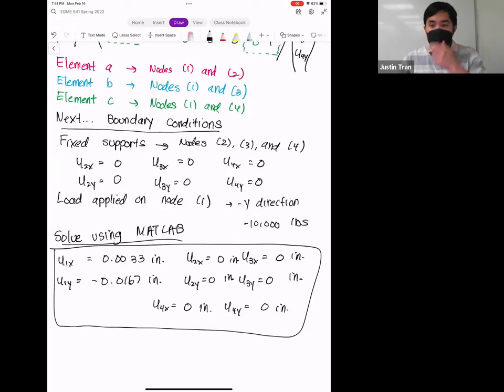All right, question. Can you incorporate this problem into Ansys? Yeah, absolutely you can. What you can do is incorporate each of these slender objects as a beam element, because Ansys gives you the ability to define these slender type elements. So very similar to what we're doing here. Then you can apply the loads exactly the same way, and make sure the material property is the same. And you should get similar solutions. Maybe not exactly, because right now we're making the assumption that our displacements are only tensile and compressive, and I think in Ansys you might have to do some special settings to set that. But you should get pretty close in Ansys to what we get here. Okay.